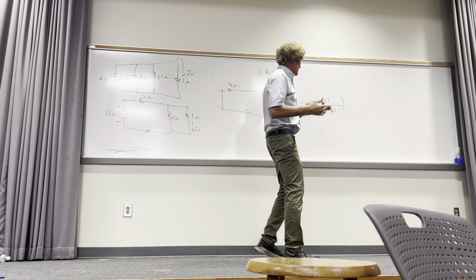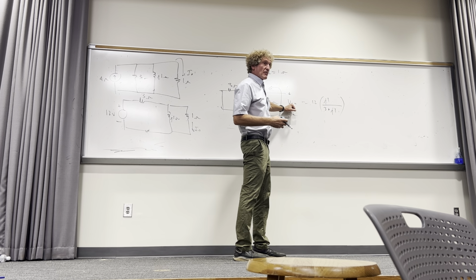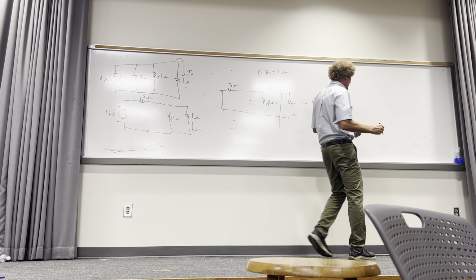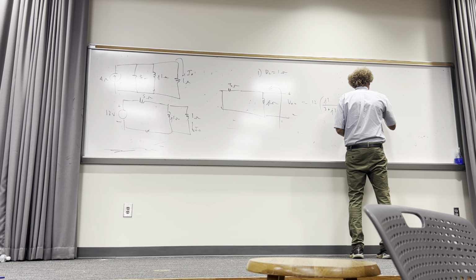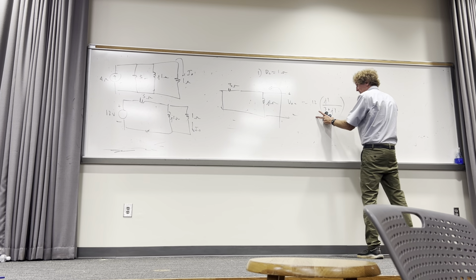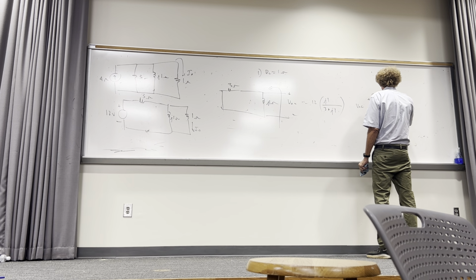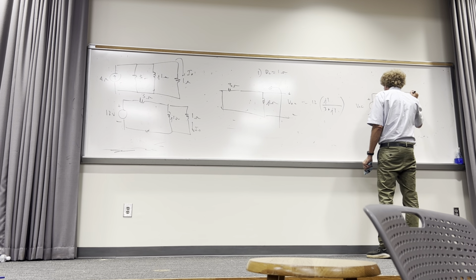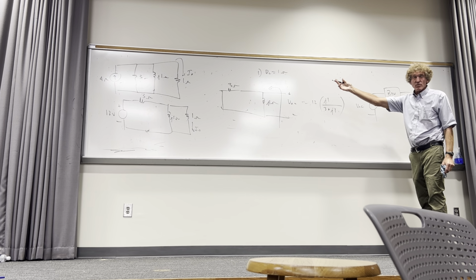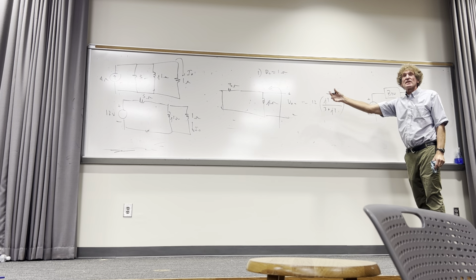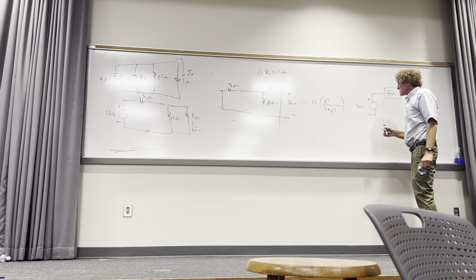In other words, and I'm not even going to bother with this, you have the open circuit voltage that would go here. And that's the value. Then you're going to have Z Thevenin here, and that is the series or the actual Thevenin equivalent impedance instead of a resistance.